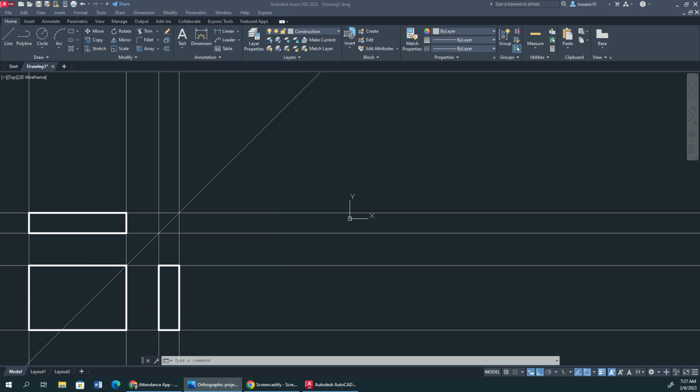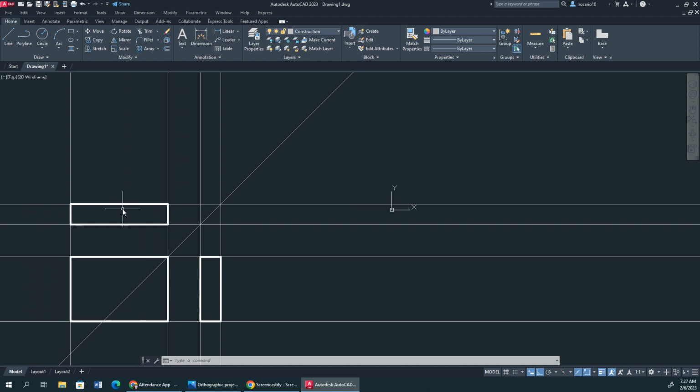So this is where it gets a little tricky, and I really want you guys to pay attention because, yes, this is new. This is also going to help you figure out how to create an isometric drawing because you're going to get the proper dimensions from this multi-view drawing, okay? So I'm going to work on the top plane, okay? I'm going to go back to Object. I'm going to click Line. Actually, you know what? I'm sorry. I'm going to go to Construction. What we're going to do is we're going to offset.